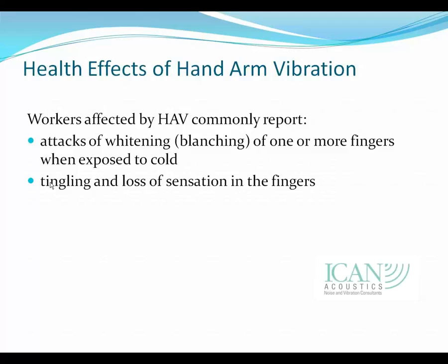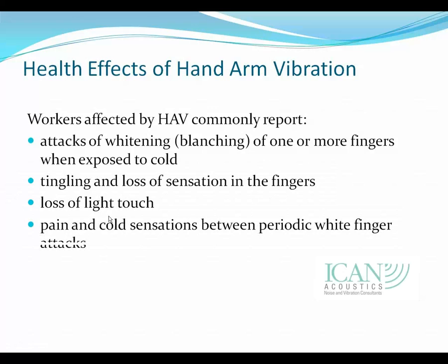Workers can also report a tingling or a loss of sensation in their fingers. Some notes would also suggest there's a loss of light touch, so the sensitivity of the hand can be affected by hand-arm vibration. Many will report pain and cold sensations between periodic white finger attacks. So it can cause pain, something to keep in mind. Another factor can be a loss of grip strength, where you lose your ability to hold something, and that would be in very severe cases.